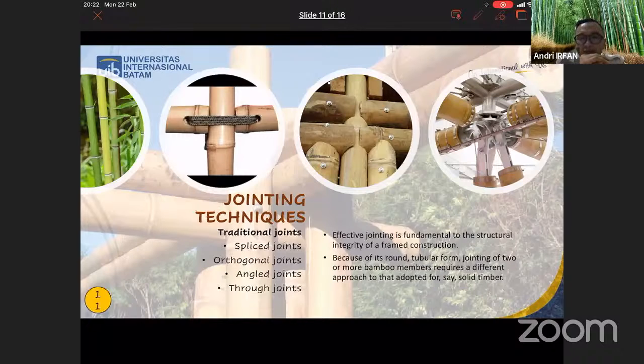Despite its relatively high strength, bamboo is susceptible to crushing, particularly of open ends, yet also characteristically has a tendency to split. The use of nails, pegs, notches, or mortises can therefore result in considerable reduction in strength. Connections or joints must also cope with variation in diameter, because the size of the bamboo is not uniform; it varies in diameter, wall thickness, and slackness.